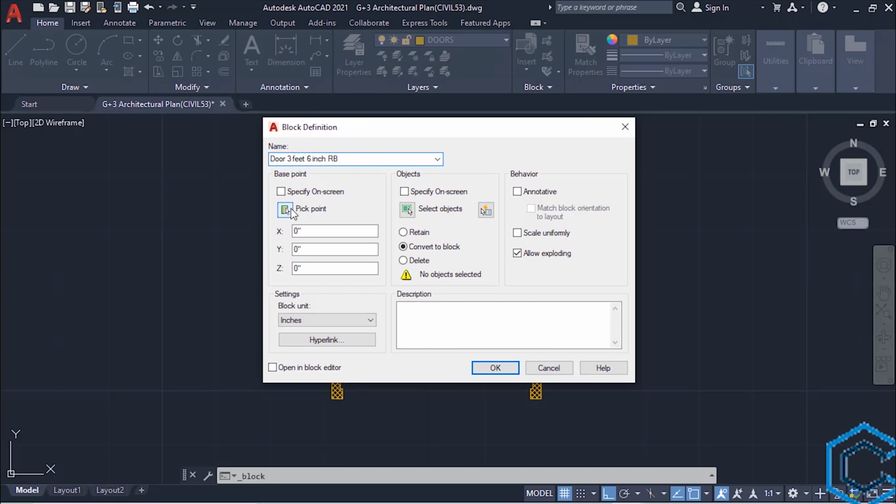Now select this line and click on this blue square, left click, and select this as a second point, so we have extended this line. Now press escape. Now type TR, enter, left click, move the cursor like this, and then left click. Press escape to come out of trim tool.